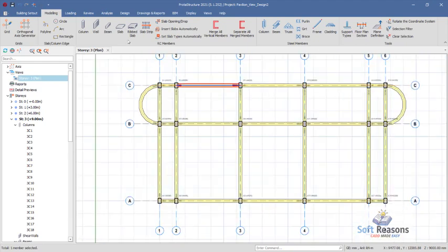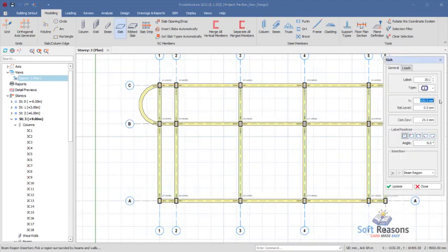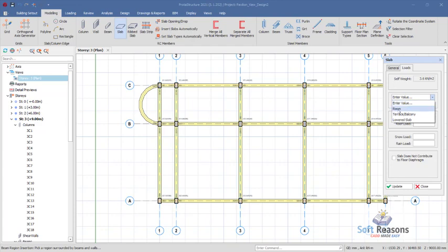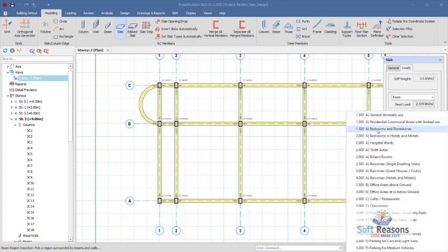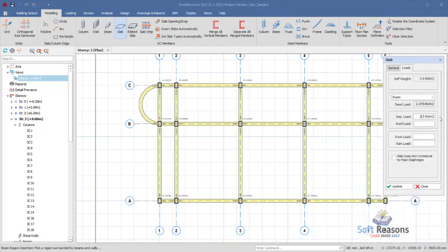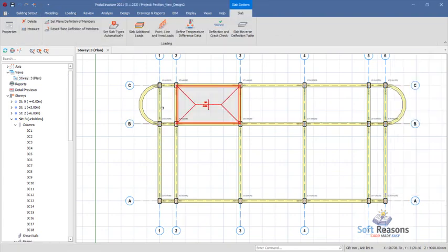At this point, select reinforced concrete slab, give it a thickness of 150 right there. Cover is 25 millimeters. You can use a room in these provisions. So we have this and this, but we may just place this here so we can use its property. There are some changes we need to make here.